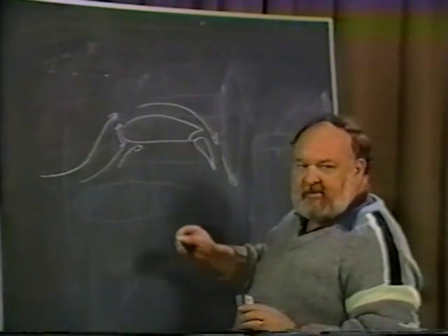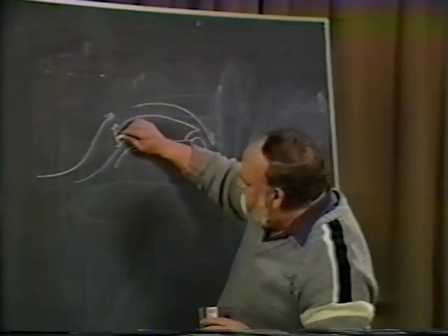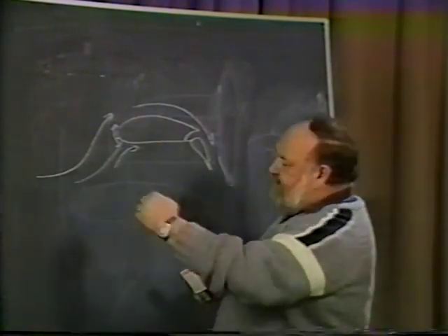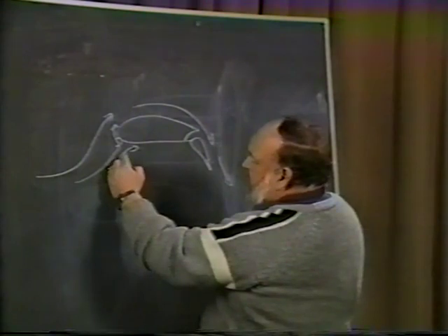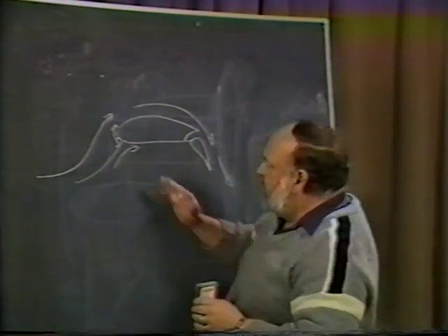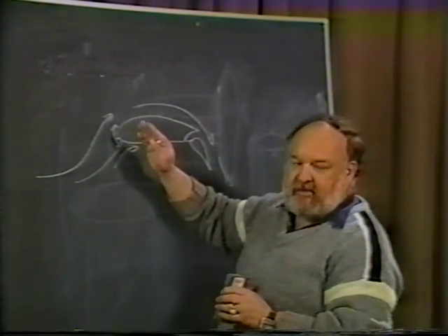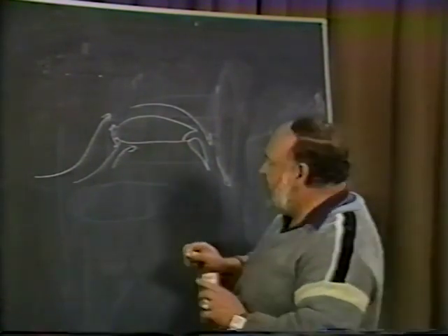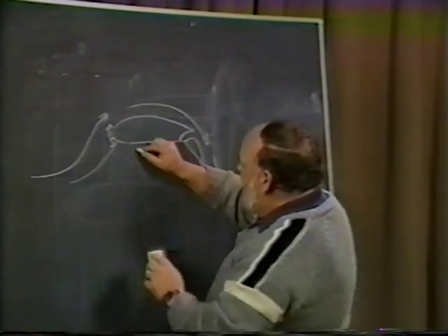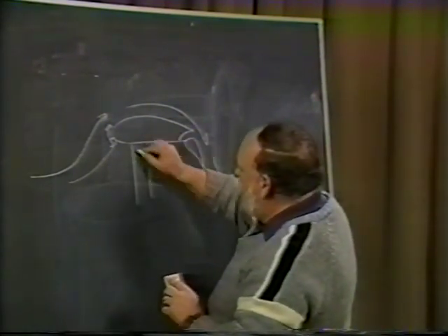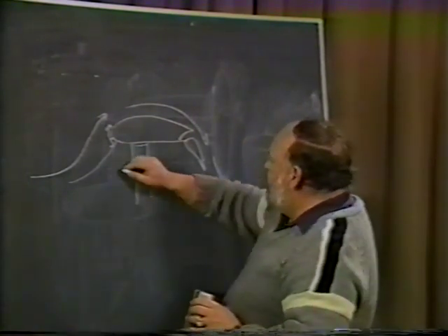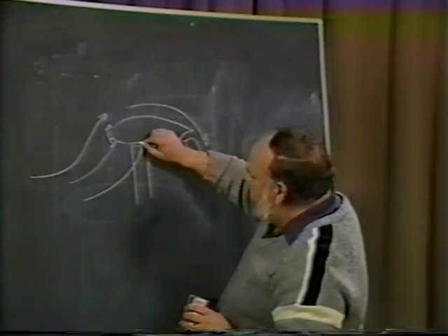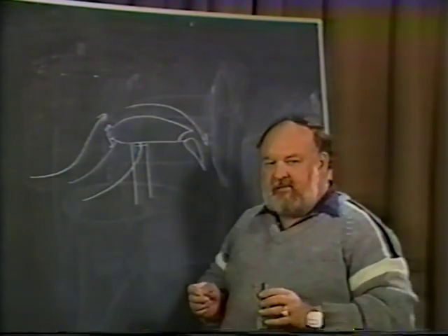I'm sure you all remember the simple little stall warning device, which was just a little tab connected to a microswitch that would stick out there. As the airplane's nose came up and the stagnation point moved behind and underneath that little tab, it pushed the tab up, which activated the switch, which gave the pilot a warning that he was getting near stall. And it worked quite effectively. Well, on the L-19, what happened is you have a strut coming down at a certain portion out in the wing, and they produced so much lift with the boundary control that the stagnation point actually came and touched the wing where the strut meets the bottom of the wing.